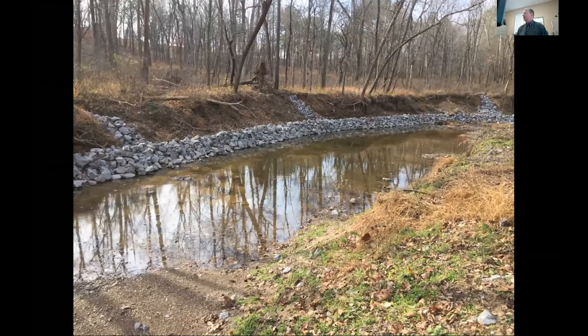So here's what it looks like right after it goes in. It's a peaked stone because it's sort of in a peaked windrow of rock, I guess you would say. And we'll talk about sizing in a little bit. And then every 75 feet or so, it'll have these keys that go back into the bank. This is to make sure that flows don't get behind this windrow and erode behind the peak stone protection.